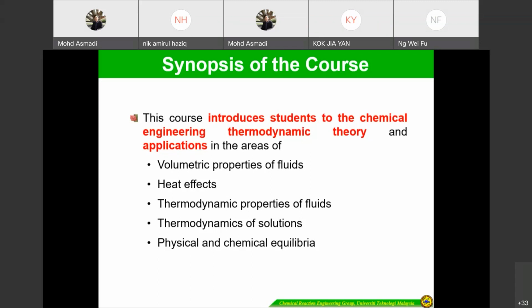So how can we calculate the pressure, the volume, or the temperature, for example temperature at high pressure, or the volume, or composition? If you learned mostly mass balance, you used the compressibility factor, PV equals ZRT, to calculate the thermodynamic properties at high pressure or high temperature. So we do not consider the ideal gas.